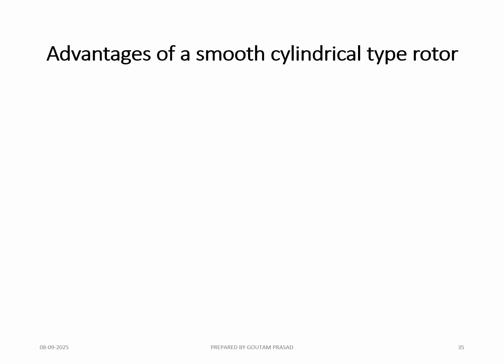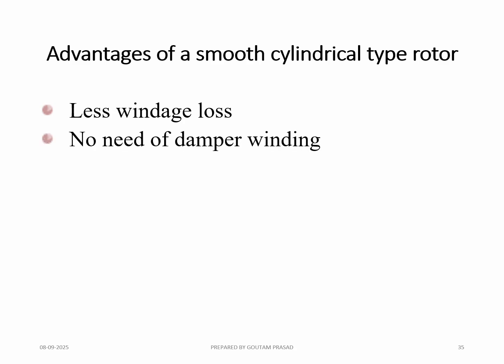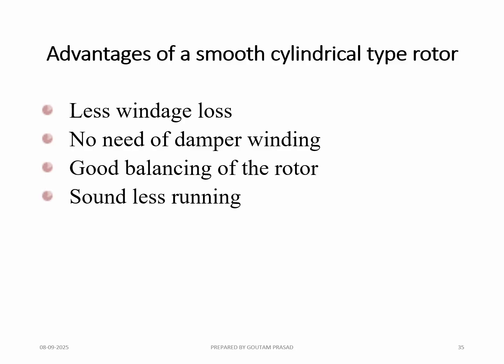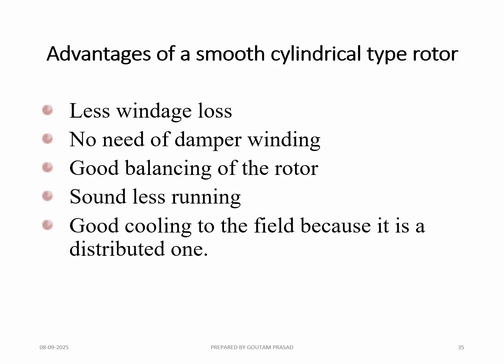Advantages of the smooth cylindrical type rotor. As we have already discussed, it causes less windage loss, there is no need of damper winding in this case, good balancing of the rotor, soundless running, and good cooling of the field because it is a distributed one.